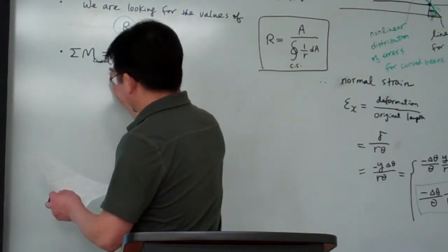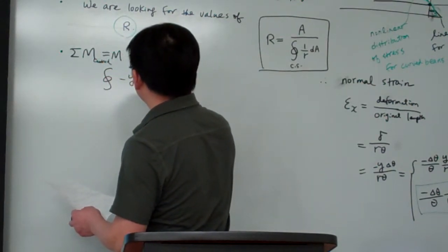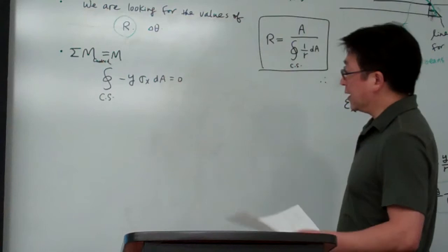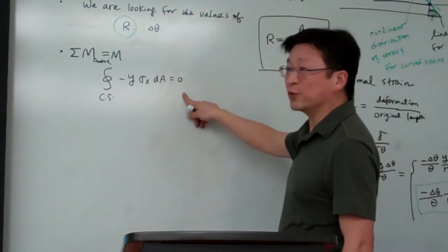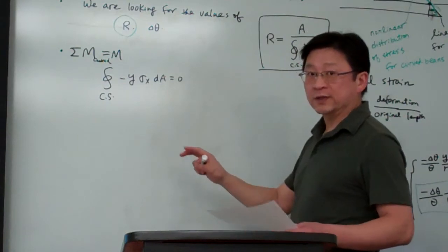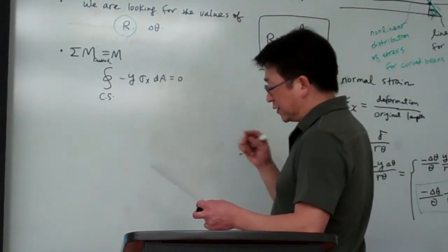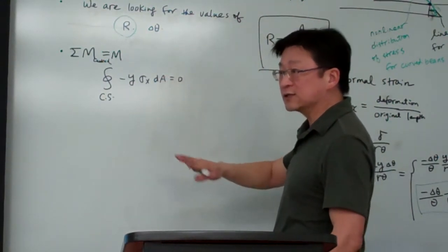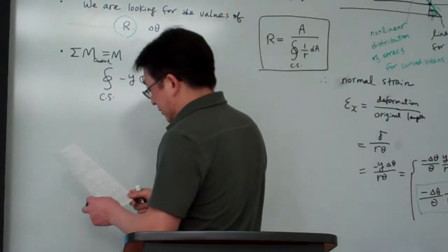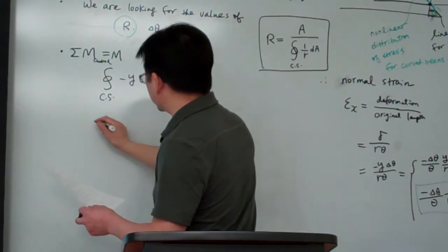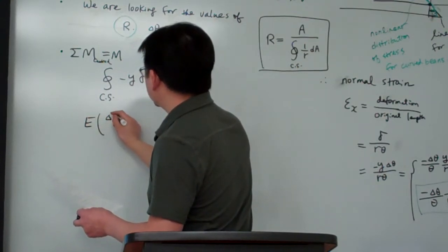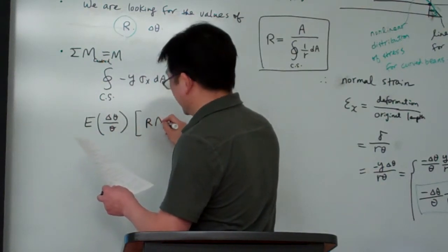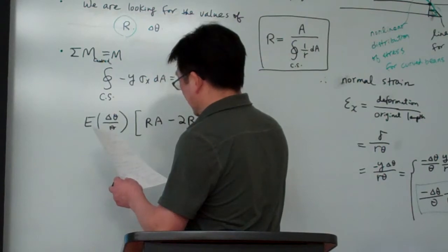So that means here is minus y times sigma x dA equals 0. And again, this is over the whole cross-sectional area. And this equation is the same as we did for the uncurved beam. Okay, the same. So for this derivation, we simply plug into this formulation and expand it. And let me give you the final result. The final result basically will lead to here: E delta theta will be equal to R A minus 2 R A plus...